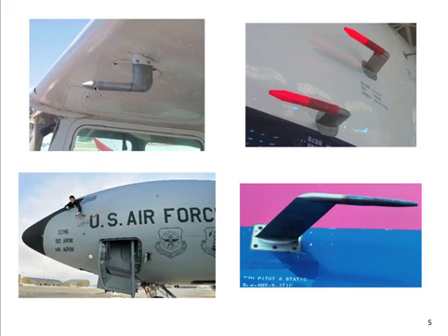Because you can't really see it here, but right there, there's a little tap, a little hole, that actually is measuring the static pressure, in addition to the little hole at the front that is measuring the dynamic pressure. The difference between the two pressures provides the quantities that we use to measure velocity.